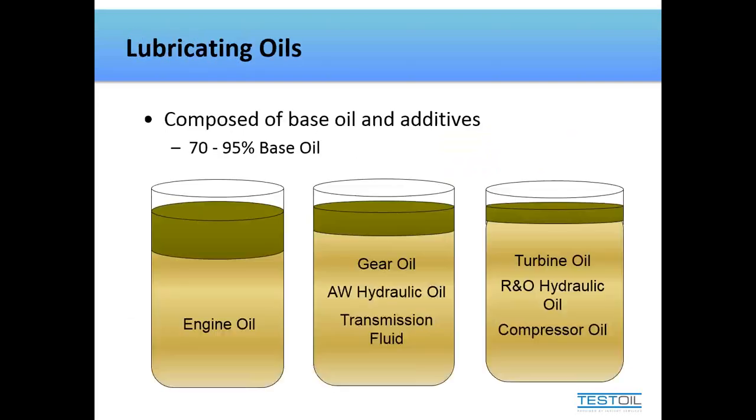Now, for lubricating oils, your basic makeup. Your engine oils are the most highly additized oils there are. This being because of the internal combustion process. You've got acids, you've got outside elements, you've got fuel, you've got fire. You get different deposits from this internal detonation of air and fuels. So to combat that, these oils are highly additized, be it cleaners, additives to reduce smog, things such as that.